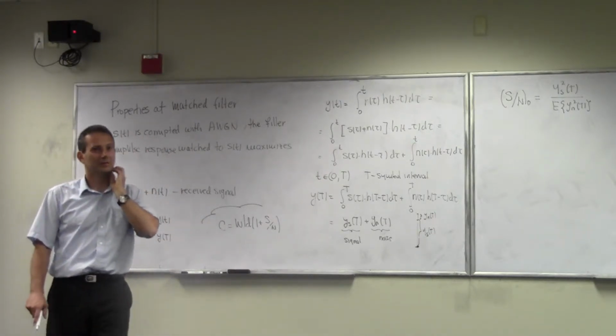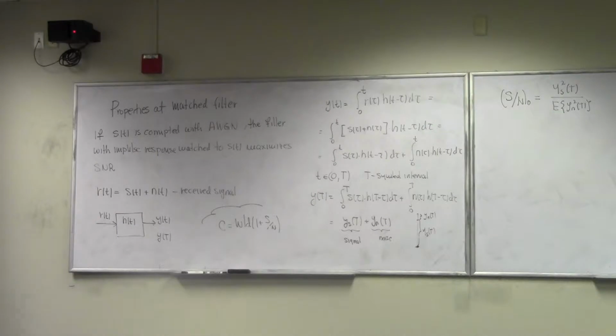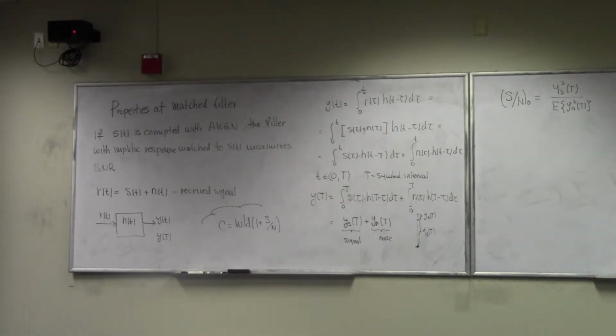Go ahead. So basically that imaginary dial you're saying goes up and down, the noise and signal. If it goes completely up, so everything contributes towards the signal, that would be an ideal case, the dream scenario, and if we can get there, it would be awesome. But we will show that you cannot really get there, and that the best you can do is your matched filter, and it would put this dial as high as it can go, but higher than that you cannot. It could also establish the limit on how good your demodulation can be.